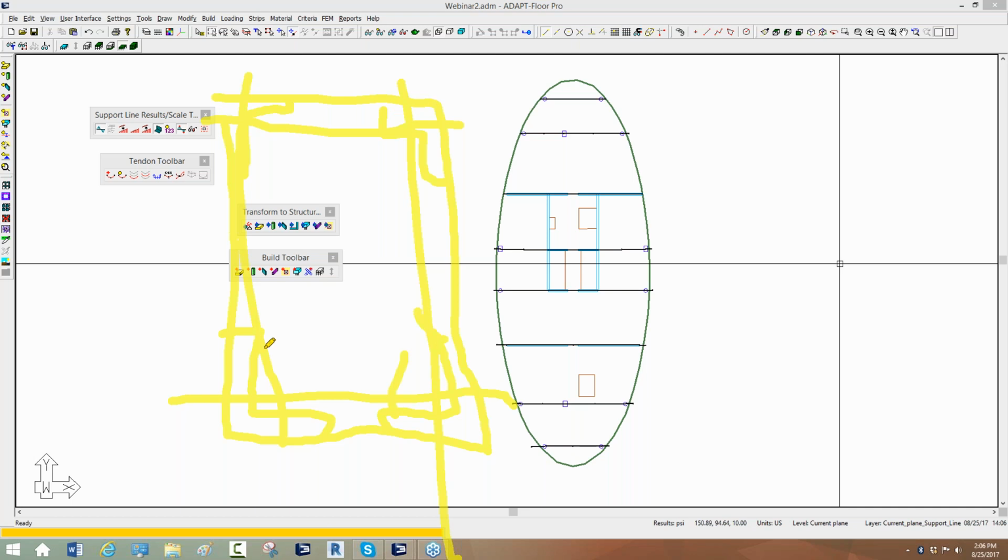So the slab has to be detailed in real life in order to mitigate the loss of precompression due to restraint, and also just to mitigate the fact that the slab is going to crack, or the wall might crack due to that stiffness of that vertical element. The program will consider that in its analysis. If you modeled this arrangement here and you fix the base of the walls and you didn't release them from the slab, and you ran the model and looked at the axial stress along these strips, you're going to see losses in axial force at the walls.